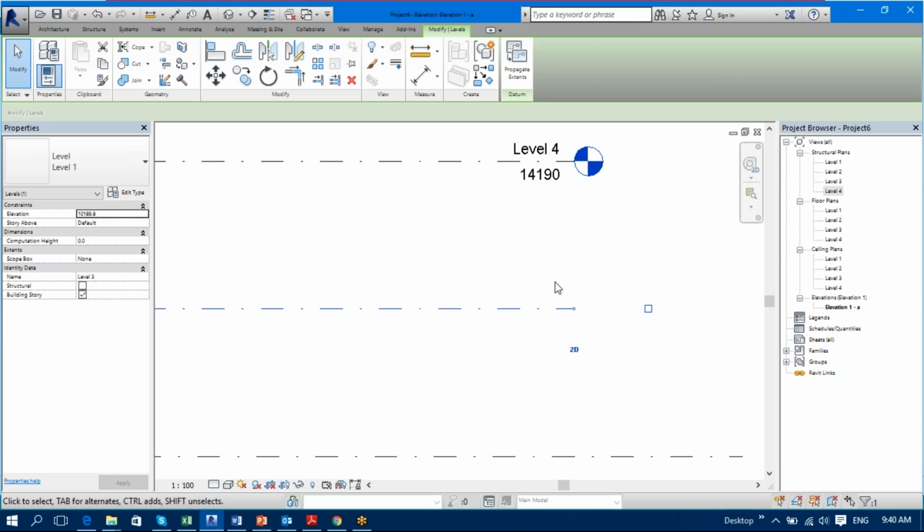This lock thing is called padlocks. These are called padlocks. These padlocks appear in every environment in Revit. Whenever you pin the element, whenever you constrain the element, dimensions and then EQ, whenever you associate with lots of different grids, whenever you put it on a single line, there would be this padlock. And when you're using families, these padlocks are very important. So we say padlocks equals constraint, dimension.